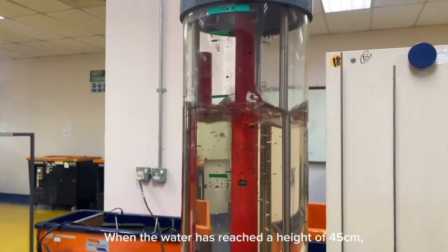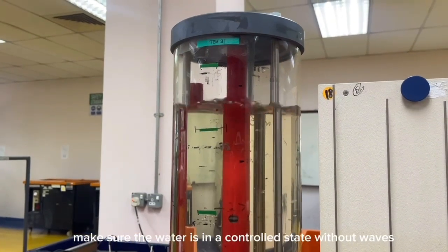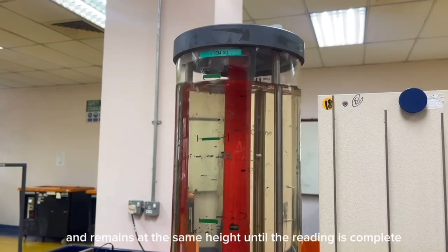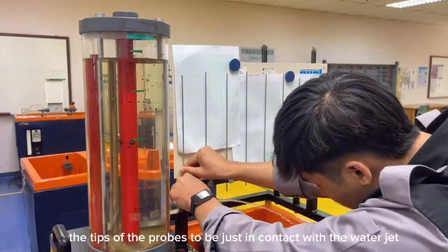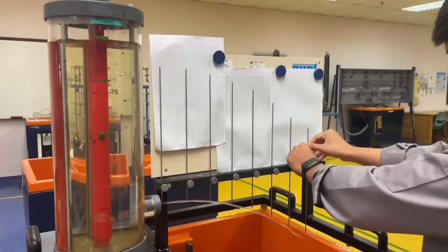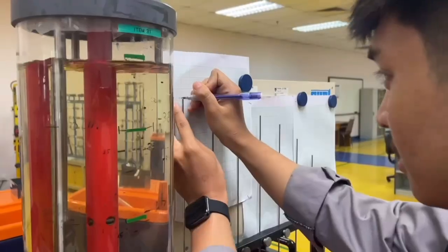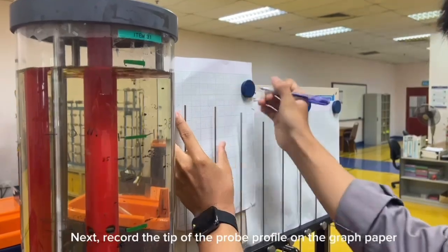When the water has reached a height of 45 cm, make sure the water is in a controlled state without waves and remains at the same height until the reading is complete. To record the data, firstly we need to adjust the tip of the probes to be just in contact with the water jet. Next, record the tip of the probe profile on the graph paper.